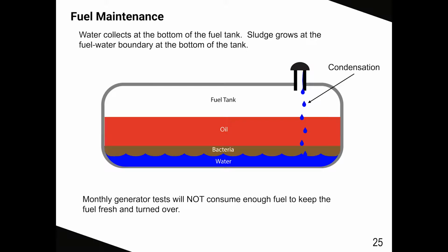Where is the pump suction drop tube? At the bottom of the tank to get all the oil out. So this means that sludge is going to your generator. It's not good.